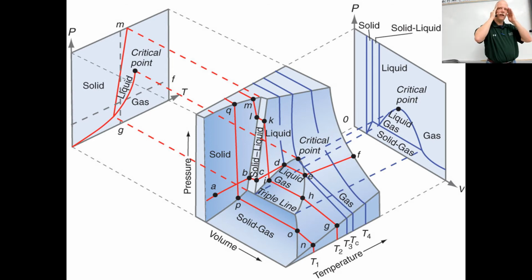Has everybody been okay following me without drawing a piston on the board? Changing this volume is a great way for me to think about a piston. It's just pushing on the substance, changing the volume. And how much pressure is needed to do that is the y-axis, the pressure. And that's what you do for an isotherm. That would be isothermal compression. If we run these backwards, it's isothermal expansion.